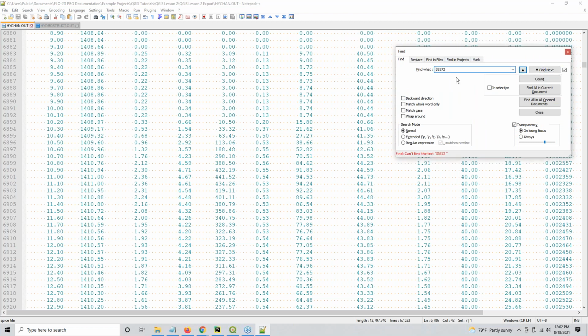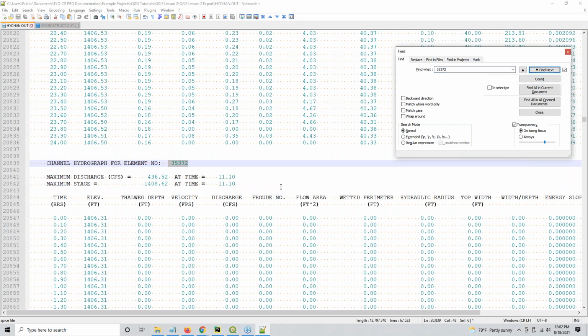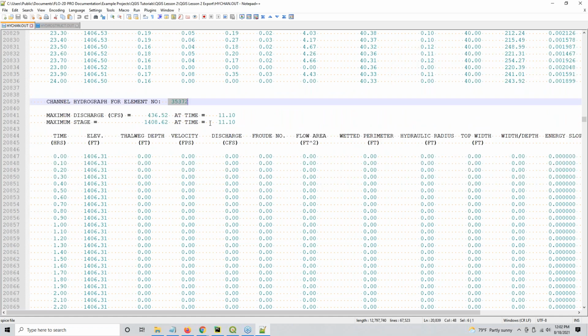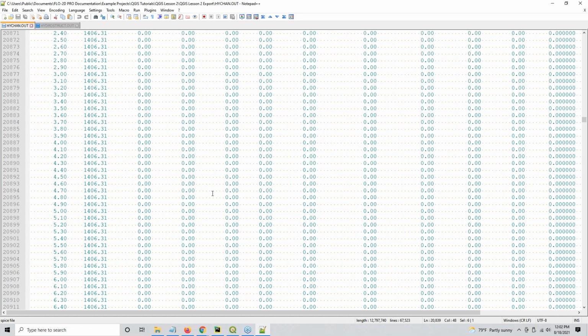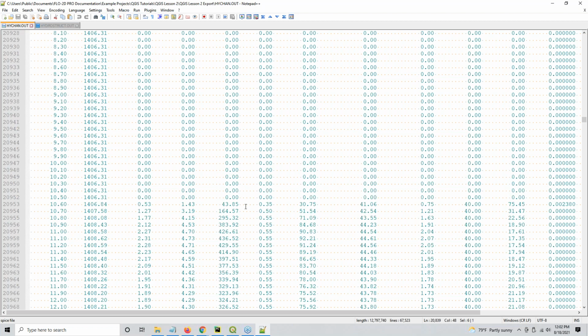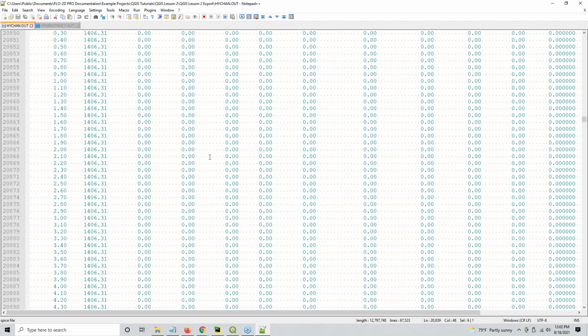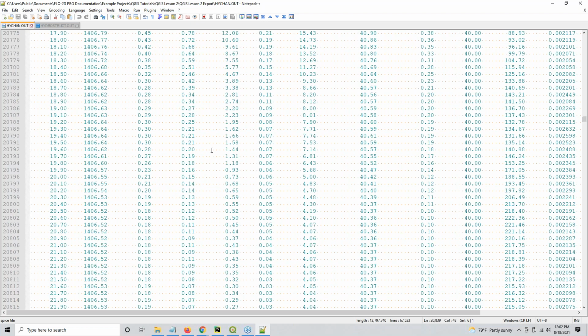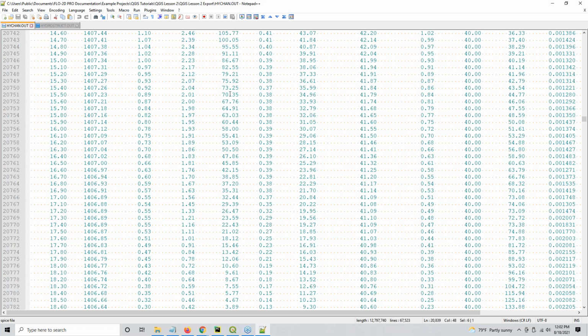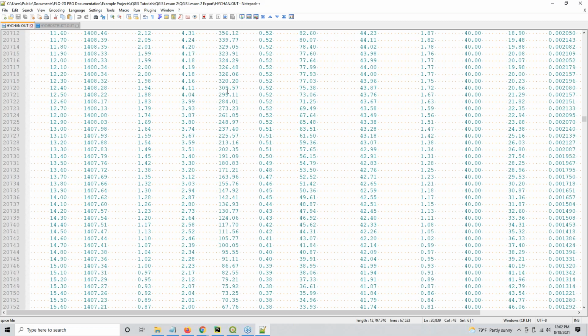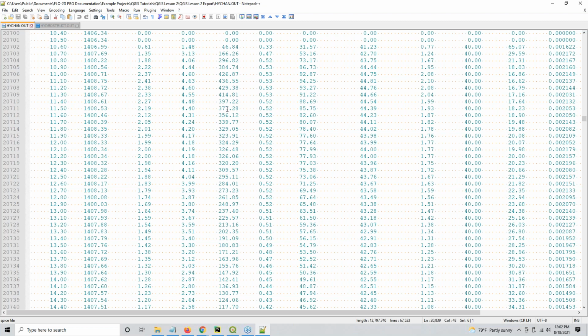All right, hang on a sec. I'm going to take that space and put another space in. There we go. So you can see here that this is my inflow at that structure. So if this value, or even if you go upstream a couple of cells, if these values start changing significantly, obviously a hydraulic structure is probably going to reduce the flow of the water coming down the channel because it's going to constrict it.